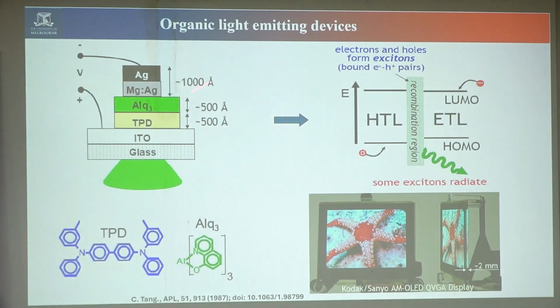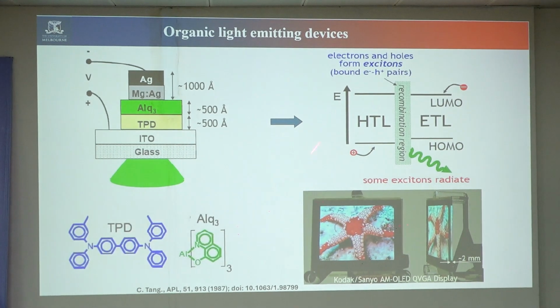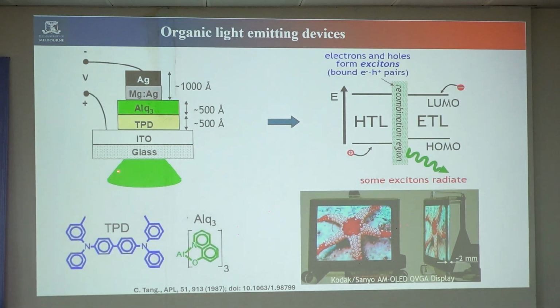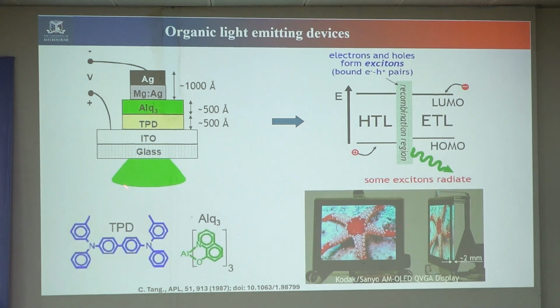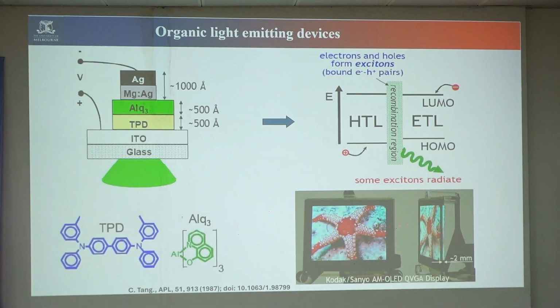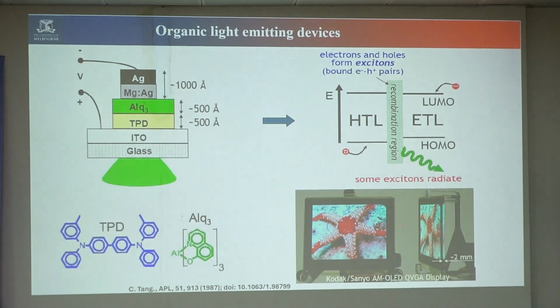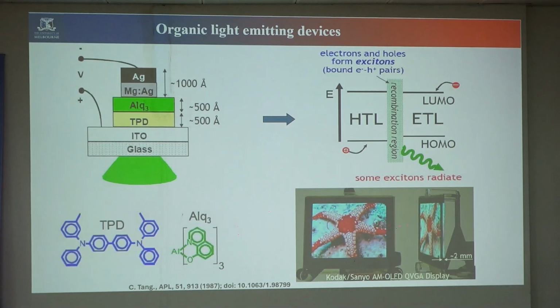As I said, we have already seen this slide in the first introduction class. The OLED is a basic device like this. They have donor and acceptor. When you talk about any optoelectronic device, you have to remember that everything is based on the exciton. You heard about the exciton. You know how the exciton is generated in the OPV device, we have already seen this in detail. In OLED, the same exciton is created because of electron and hole injection. If it is separated, charge is generated. If it recombines, then light will come out. So the exciton is the central point.